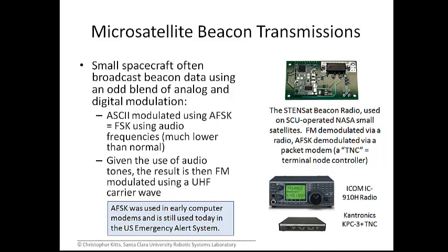So now the ham radio community has used that, and a lot of that equipment and those techniques are very simple, very inexpensive to use, with a lot of built-up infrastructure and knowledge centered around that. So they do that as a first step, and they do that in a process that typically is executed in a piece of equipment called a terminal node controller. And this does that first phase of modulation, and it also does a lot of command and data handling functions like packetization and things like that.